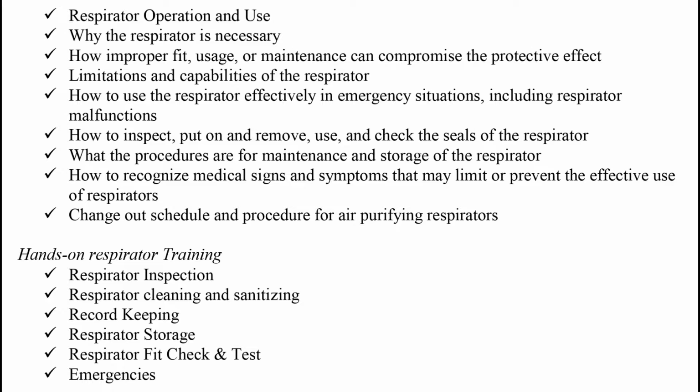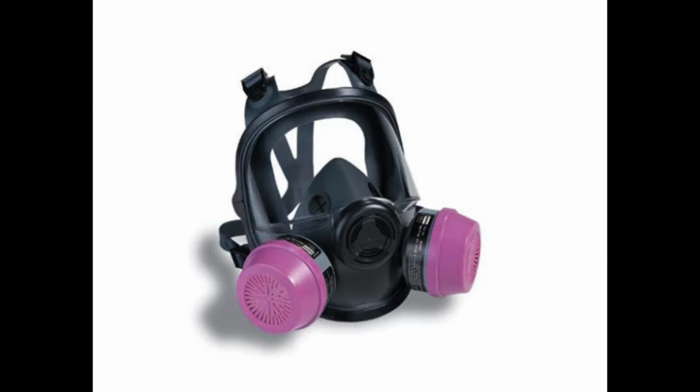Hands-on respirator training includes respirator inspection, respirator cleaning and sanitizing, record keeping, respirator storage, respirator fit, check and test, and emergencies. Basic respiratory protection safety procedures. Only authorized and trained employees may use respirators. Those employees may use only the respirator they have been trained on and properly fitted to use. Only physically qualified employees may be trained and authorized to use respirators.